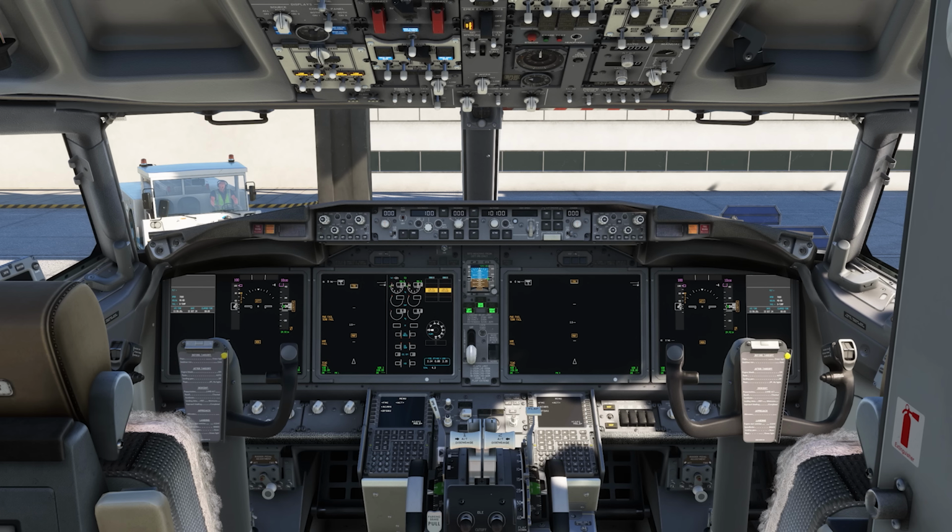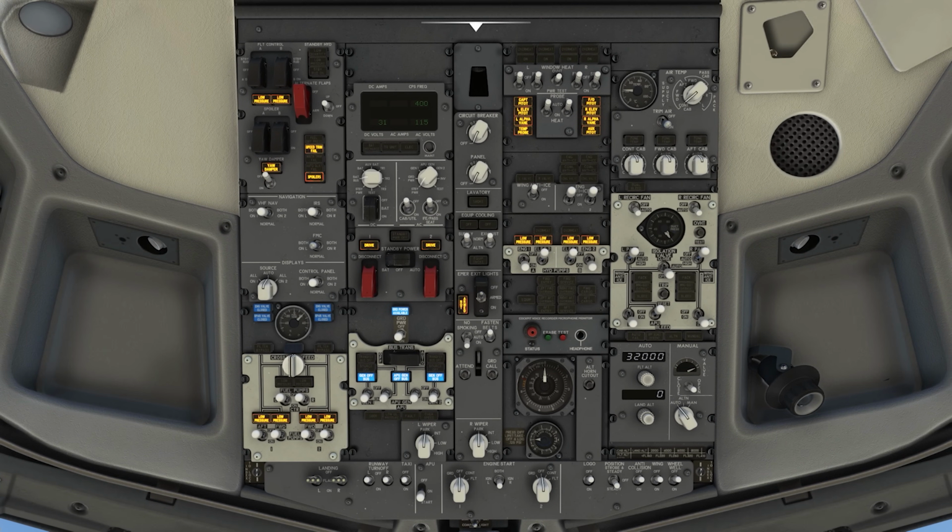In essence, not much has changed. There are just some subtle differences in the light logic, and there's also a brand new core anti-ice system, which is part of the CFM LEAP 1B. So what is the core anti-ice system? It's an EEC controlled anti-ice system which is completely automated and transparent to the flight crew, and it directs bleed air through the engine core as needed. If there's a fault with that system, the engine anti-ice light will illuminate, and it's part of the checklist when we're trying to identify the fault.